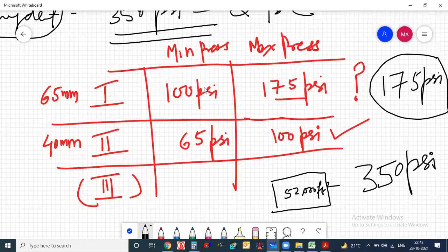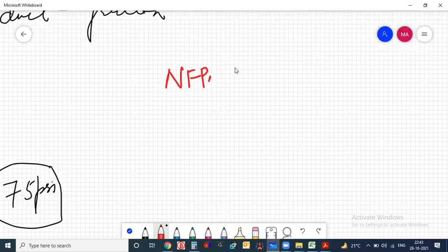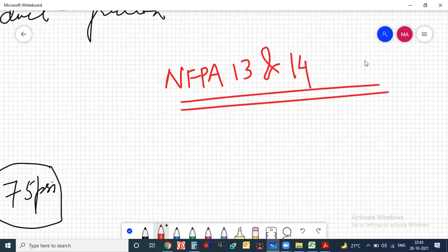Mr. Atif, yeah, tell me. Hello, can you hear me? Yeah, I can. In the hose reel cabinet, there is single and there is the double cabin. In the double cabin, you will have the hose reel, which is 40 mm, and you also have downside a landing valve, like a coupling, and there is a big hose. Is this the combined class 3? No, because 2 inch and a half is downside. Double cabin, you know the double cabin, right?